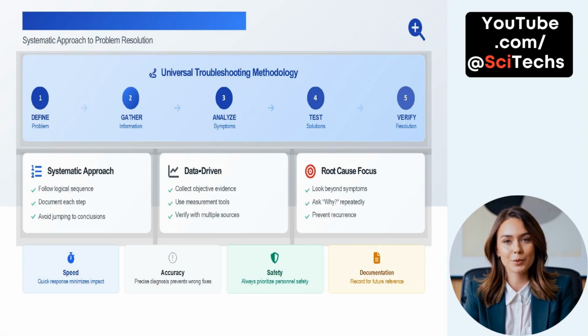Systematic approach to problem resolution. A universal troubleshooting methodology is essential for effective problem solving in semiconductor equipment. This process begins with defining the problem, clearly identifying the issue without assumptions. Next, gather relevant information, including equipment logs, operator observations, and sensor data.